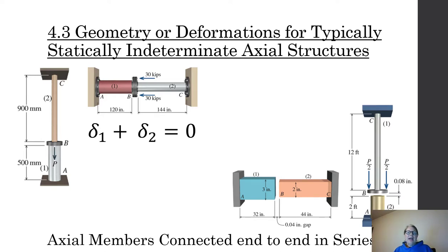I am applying a force at the collar, and maybe materials 1 and 2, I'm heating them up. Maybe I'm heating them up, okay? Because if I heat them up, they're going to both increase until I kind of touch, and then I'm going to be pushing. So when I heat it up, I may not see that there's a force in those members, but if I heat them up and they close that gap, all of a sudden they're pushing against each other.